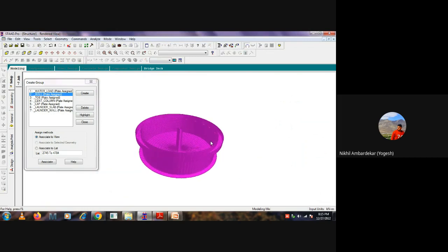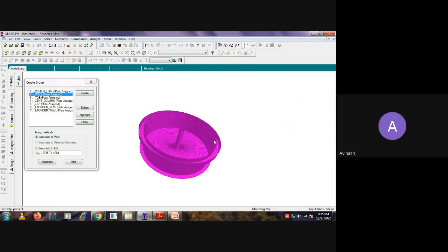If you can see this, we have created some openings. It is visible like this. Okay. So you have to repeat this here also. Based on the total number of openings, you can delete some plates. Because of that wall, there will be a little bit of stress concentration around that opening, so we have to take care of that. Otherwise, because it's at the top, it is always subjected to very little water pressure.